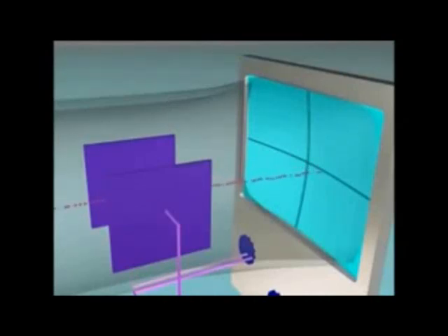Horizontal deflection. When the plates are arranged vertically, the beam of electrons is deflected horizontally across the screen from point M to N and back, as the polarities are reversed. Since the deflection is horizontal, the plates are referred to as X plates.